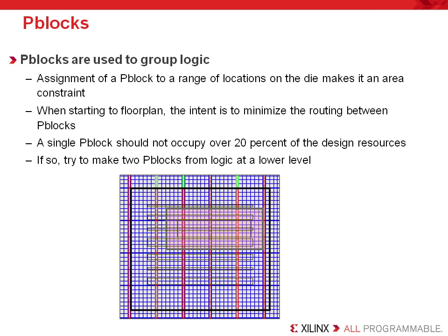You can group critical or associated logic together into a single Pblock, which prevents logic migration, limits interconnect length, and reduces delay. Creating a Pblock results in an area group constraint that is written into the exported UCF constraint file. The constraint in PlanAhead reflects the assigned logic, specified ranges, and defined attributes.